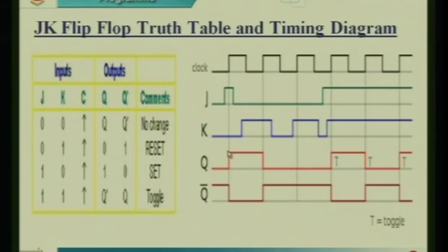So my output is set to 1, that is Q becomes 1. So next, coming to the next clock edge, my J is 0, K is 1 over here, so it is reset condition. So now we have got the output as 0. Similarly, at the next clock edge here, 0 and 1, same, it continues here.